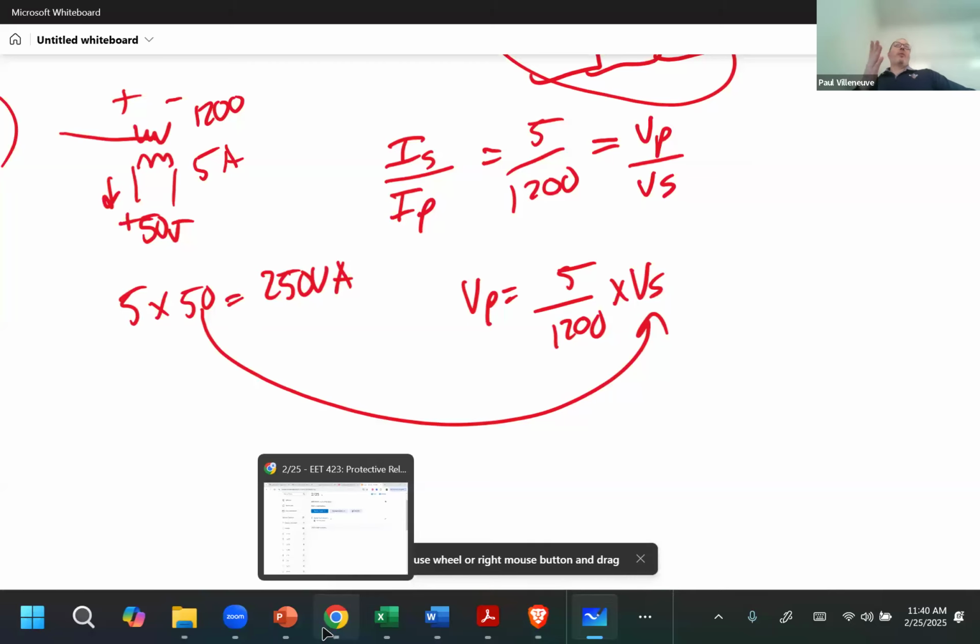Well, this is perfect. Aaron's bringing up a really good point. He put something wrong on his page. Just go back to, transformers are basically constant power devices. If you step down the current, you've got to step up the voltage. So you can easily see, hey, wait a minute, if your voltage went from 50 volts to 10,000 volts, but the current went down, how'd the power stay the same, right? So that's when you can sanity check your work. That's test number 1.